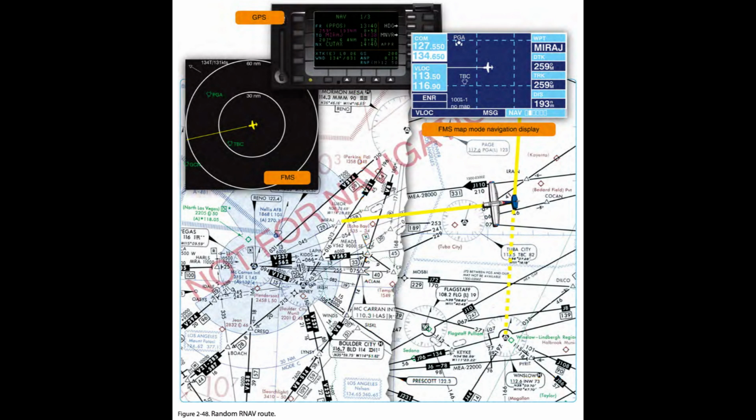below established tolerances. A remote status indicator also may be provided through the use of a signal sampling receiver, microwave link, or telephone circuit. Older FAA NDBs and some non-federal NDBs do not have the internal feature, and monitoring is accomplished by manually checking the operation at least once each hour.